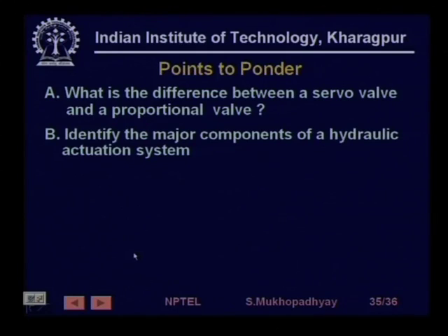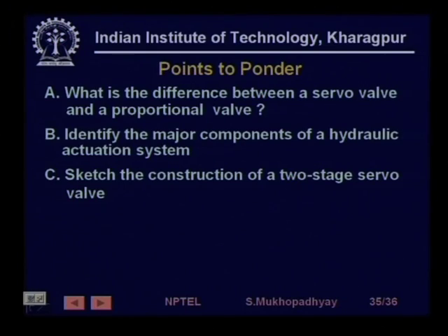Identify the major components of a hydraulic actuation system. This is one of the major questions you should be able to answer, because this is one of the basic instructional objectives. Sketch the construction of a two-stage servo valve. This is going to take some time, but think about how it works, especially how the feedback works.